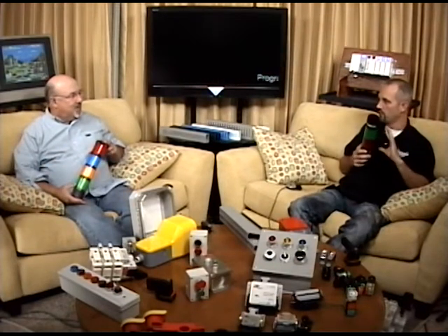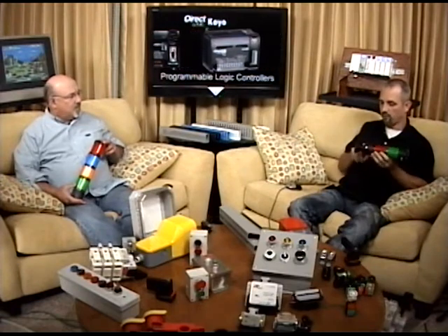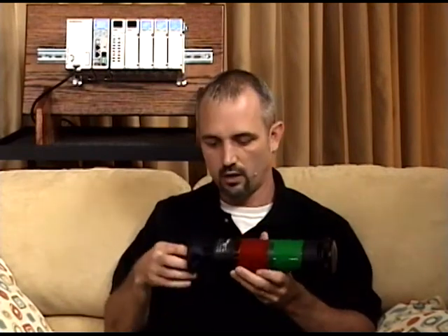But multiple colors, you can get them in strobe, you can get them in LED, you can get them in incandescent. The one I've got here in my hand actually has the audible alarm on top. You can get different size shaft bases here, the screw-on base. If you don't want to use the bases, you can actually just use 3/4 inch conduit. We've done that just straight out of the top of an enclosure and use 3/4 inch conduit, and it's got a nice little set screw. Do up to six lights high.